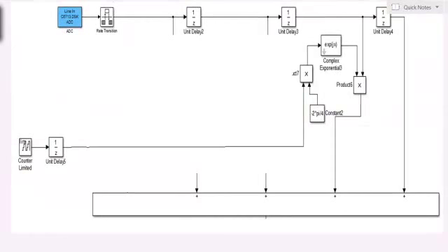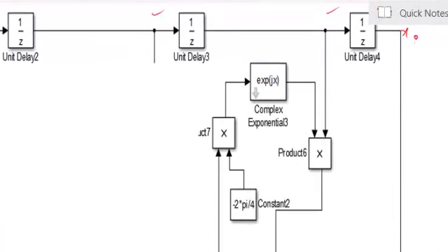So this is part of the Simulink model that you need to use in the lab to calculate the DFT coefficient. The incomplete parts have to be filled out and completed by yourself. You can see that we have the Z inverse models to create delay. Don't forget that if the samples are coming from A to C, then after a few transitions, this is always going to give you x0, x1, x2, and you have x3 here.